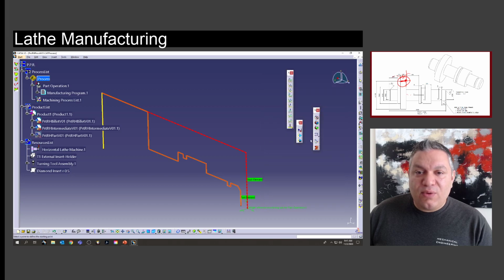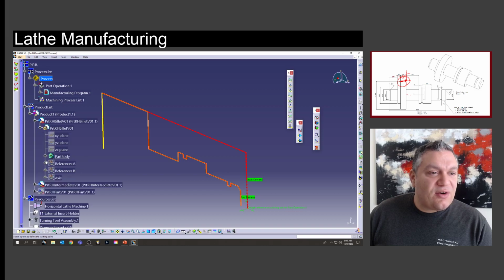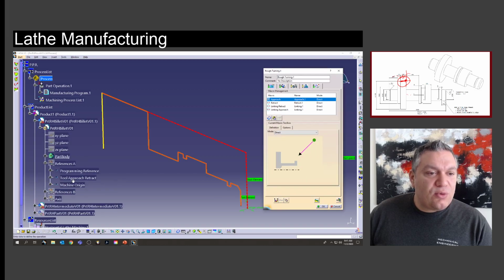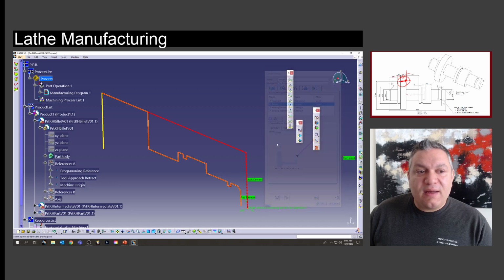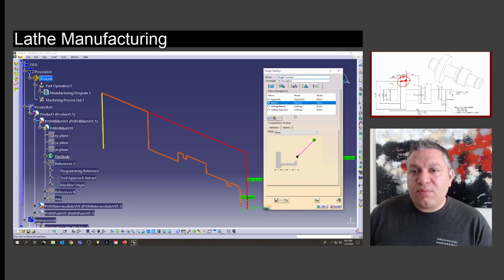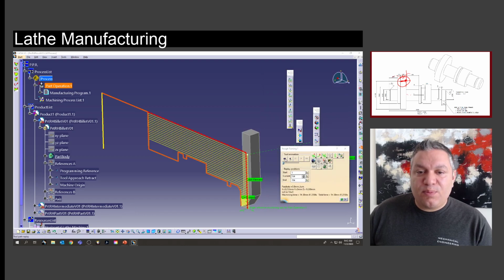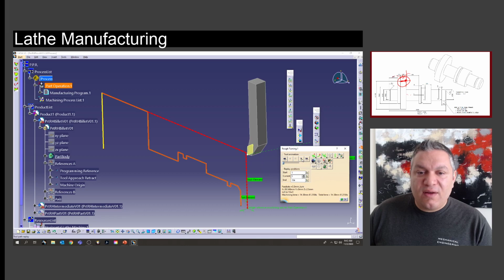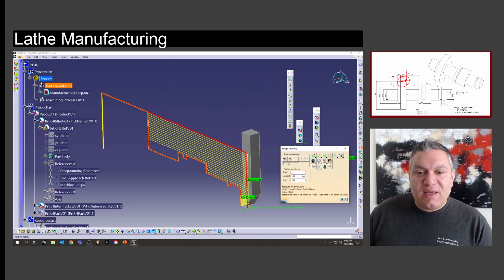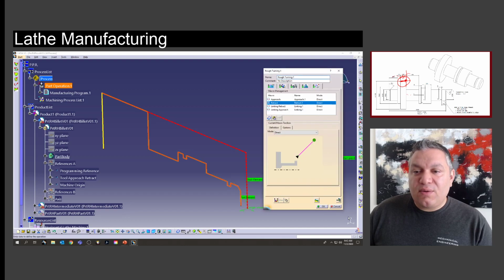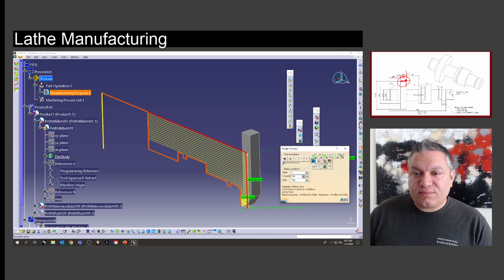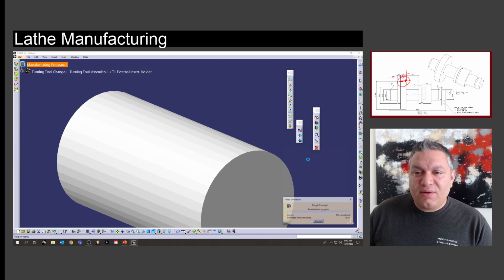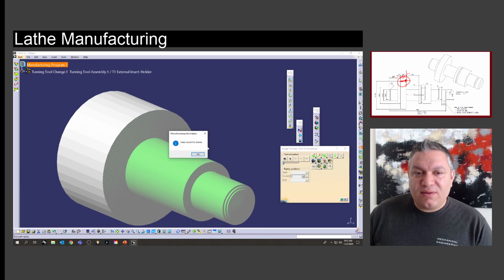So we're going to activate the approach, and what we're going to always click is reference A. So we're gonna use the tool approach retract from here. And sometimes we're going to be innovative in this, and that's fine. You press, this is the tool motion that you have, and this is the expected result for a roughing operation. All right, so let's go ahead and continue. I know I said I'm gonna take a break, but I'm excited, so I'm just gonna keep going.